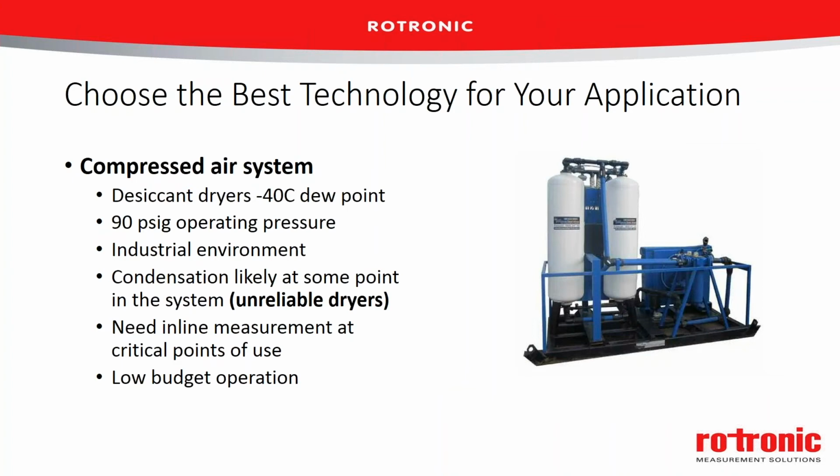Bruce, can you lead us through compressed air systems? Yes. This application, we're talking about a compressed air system. In this particular case, it's a dry system. The desiccant dryers dry the air ideally to minus 40 degrees C dew point, which is very dry. We're operating at 90 PSI gauge.